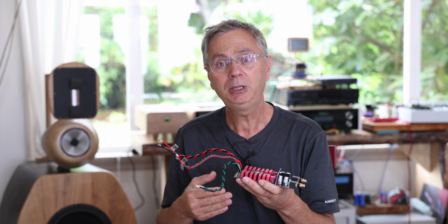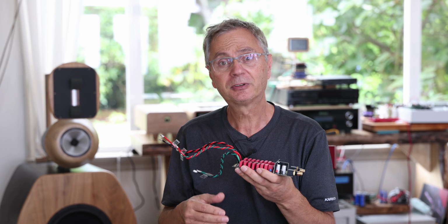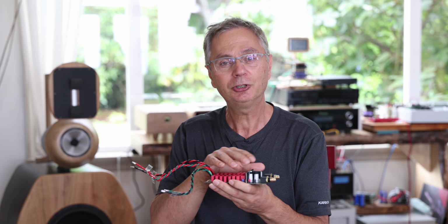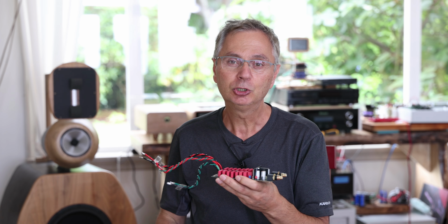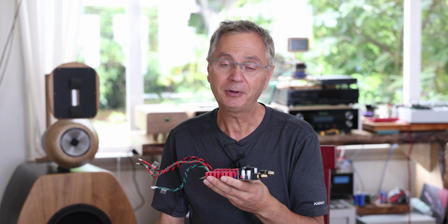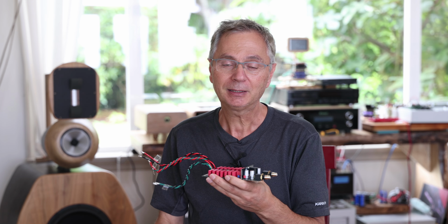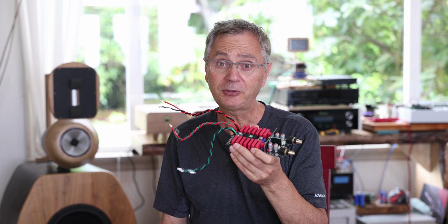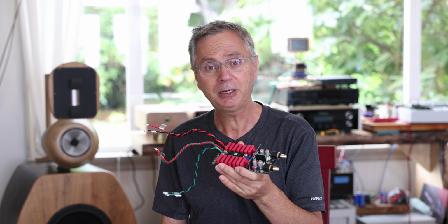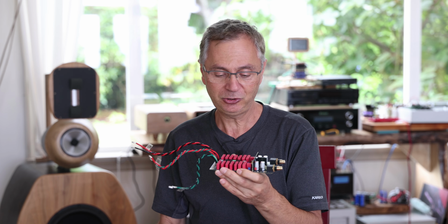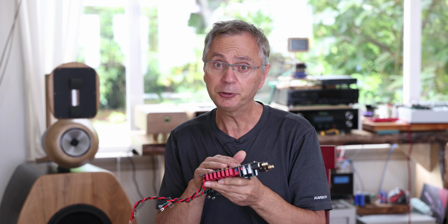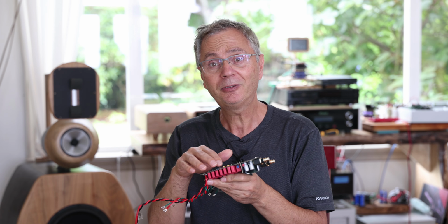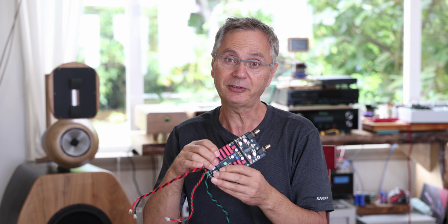The sequence should be powering your streamer first, then powering the TD1 DAC. Then you're not going to have any DC offset going into your amplifier or your speakers. But again, to be on the safe side, like I said, just put the volume a little bit lower. First time, test it with a cheap amplifier and cheap speakers, just to be sure that you did not mess up the soldering. You don't have any sloppy solder joints that are shorting things or sending power to the wrong places.